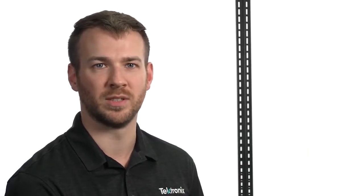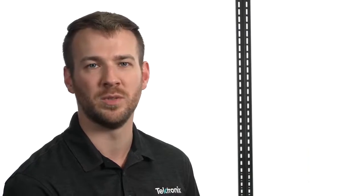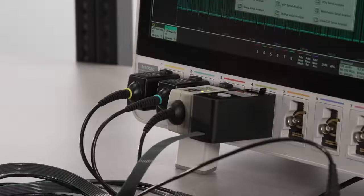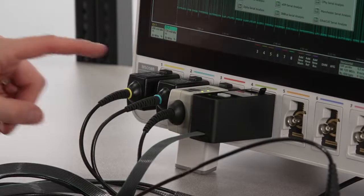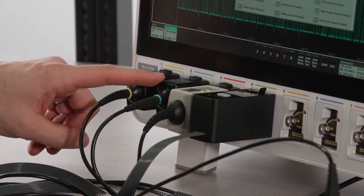Okay, first up is CAN. CAN is a relatively slow bus that uses differential signals to cancel out the high levels of noise present in automotive systems, where it's used most often. I have a passive probe in channel 1 connected to CAN H, and a second passive probe in channel 2 connected to CAN L.